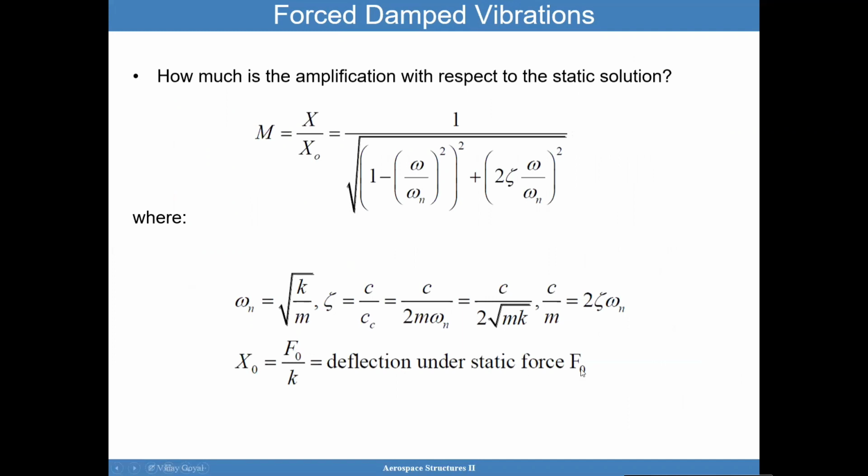So if I apply that force statically, then this is X naught, and I can determine, if I apply the force in a harmonic way, how much more it amplified. You can see here that if this symbol, which I've defined as the ratio of the coefficient for damping divided by critical damping, is considered, and I look at omega divided by omega n, and this was close to 1, and this was close to 1, this goes to 0, and the amplification is driven by this ratio.